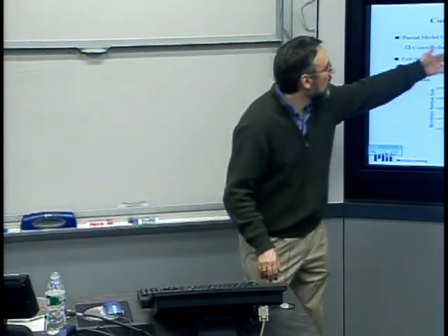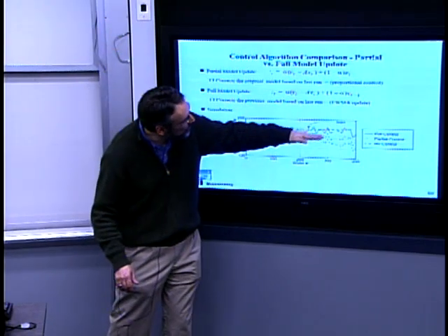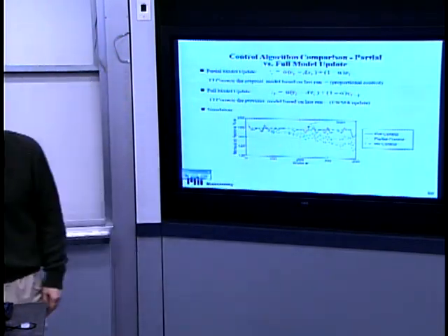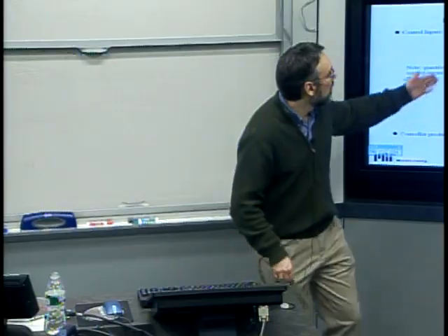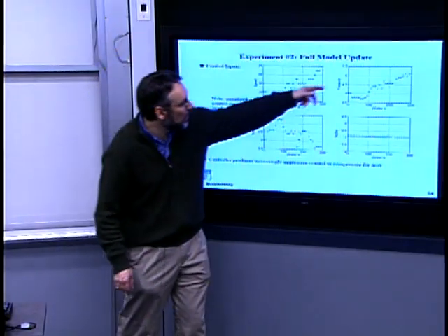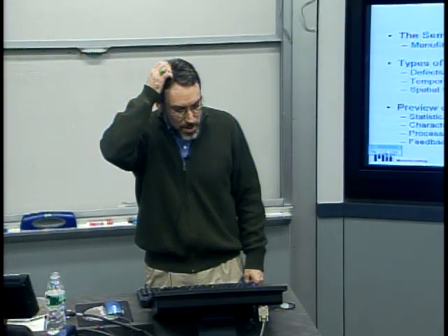And so this is just an example. You can imagine that using these simplified models, one can have some compensation strategy that brings the removal rate back up to target. And so we'll talk about that in the latter part of the term as well. These are just examples showing for different numbers of wafers, you have to actually change the speed or the pressure downforce, but you can get very good control of the output.